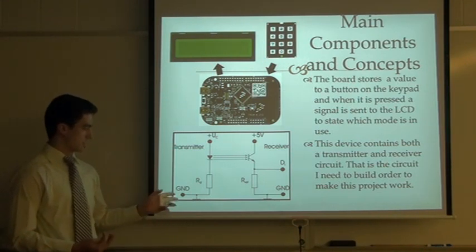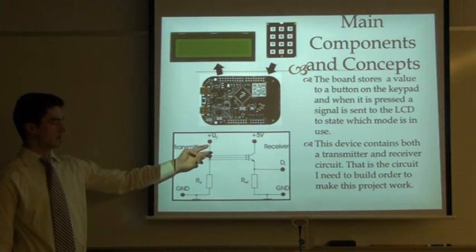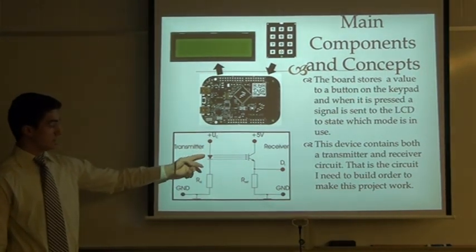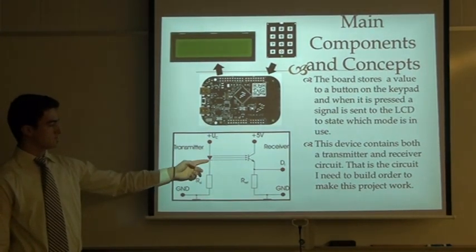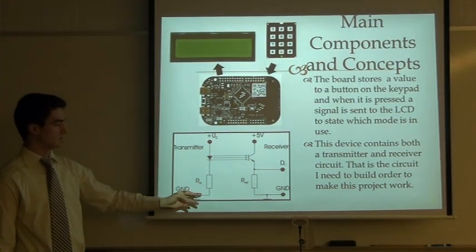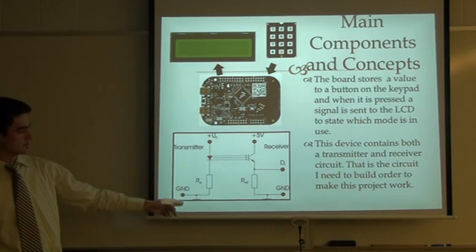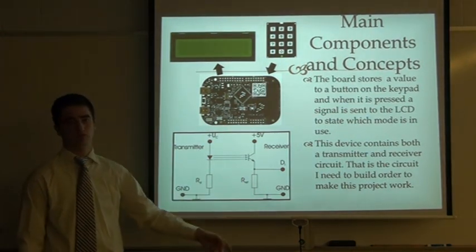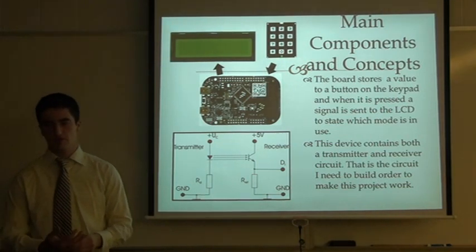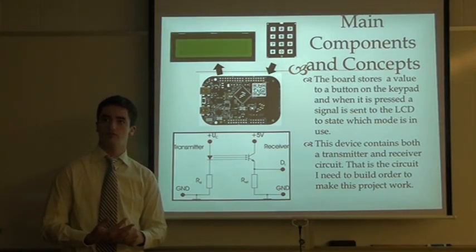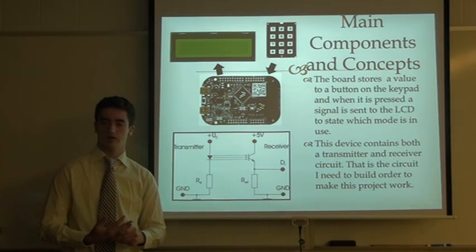Basically, you have your connection to your microcontroller, which is the Freedom board. In this case, you have your transmitter diode going through a resistor to limit the current, going to ground. And then you have coming in a 5-volt source, potentially from your Freedom board, because that has a 3 to 9 volt power supply on it.